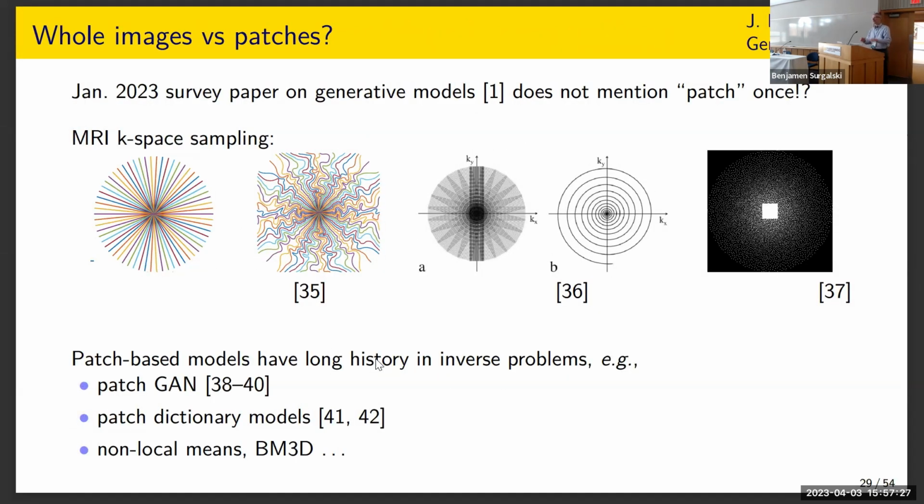So in MRI, we collect samples in the two-dimensional Fourier transform space of the slice that we're imaging for 2D MRI. And we have lots of different ways to do that. The simplest way is just collect all the samples, get a two-dimensional Cartesian grid, and just do an inverse FFT, and 90% of clinical MRI scans are done that way. But if we want to make the scan go faster, we don't collect all the samples. We collect a subset of samples, or we sample in a non-Cartesian way. And these are examples of some of the non-Cartesian sampling trajectories that we use in K-space, in spatial frequency space.